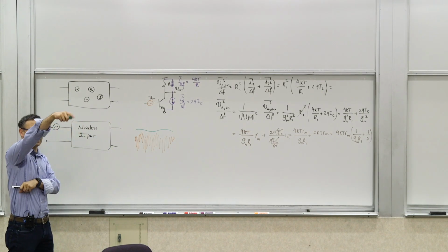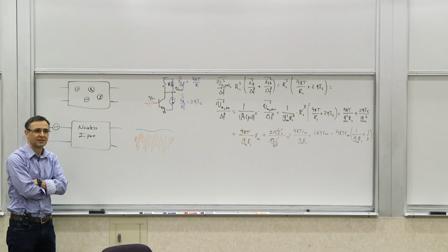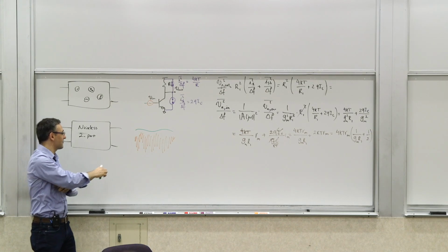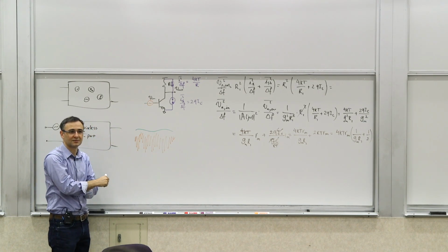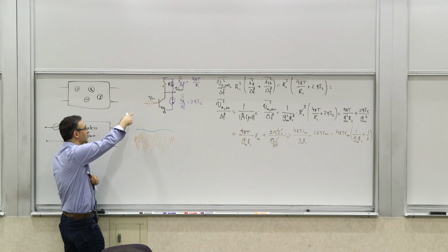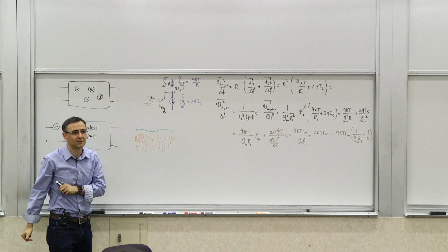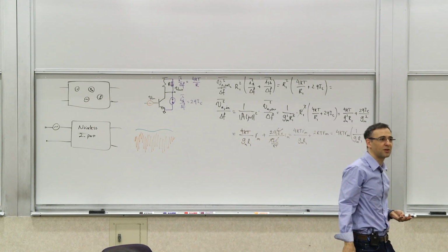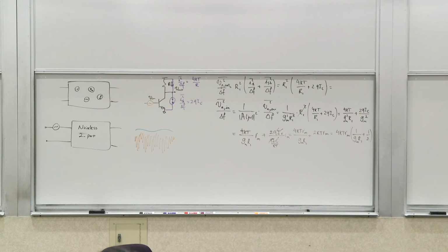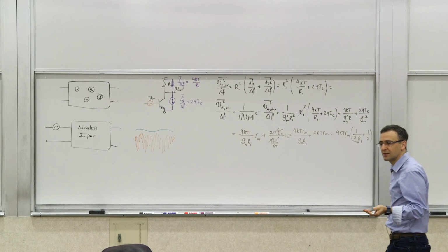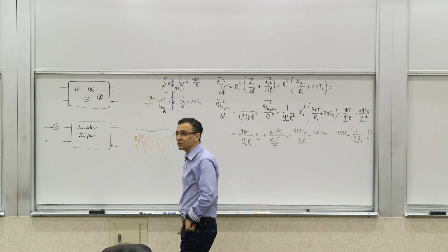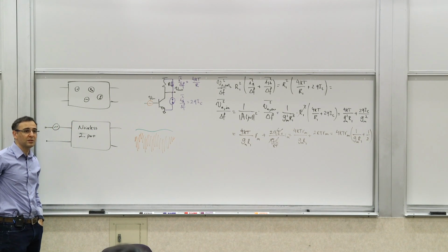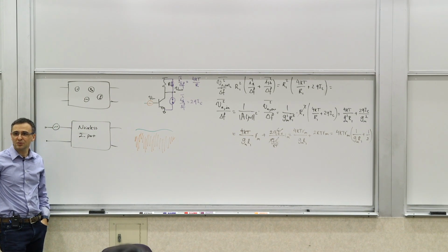So you have a voltage source that's open on one end. If that bothers you, think about a very large resistor on this side. So you have a voltage divider between a very large resistor and R pi. So most of your voltage will drop across the very large resistor. Now, if that very large resistor becomes infinity, then no voltage drop across R pi. Right? So what does that tell you? But does that mean that there's no noise at the output if I drive this with a current source?